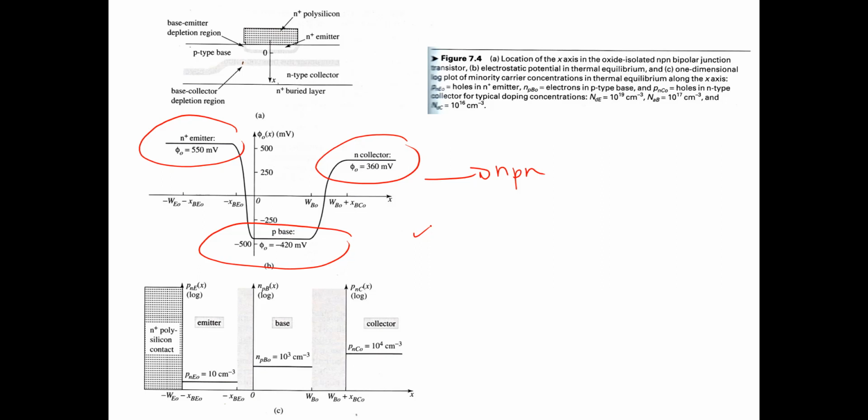So the working principle of the bipolar junction transistor is that we can deliver current from the collector to the emitter by controlling the base. So in a BJT we control the current. So it is a current controlled current source. So this is the BJT, and for the FET it is a voltage controlled current source.